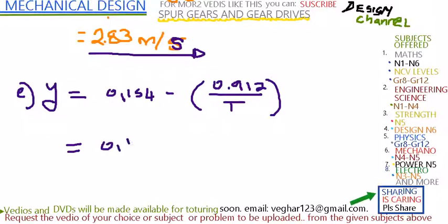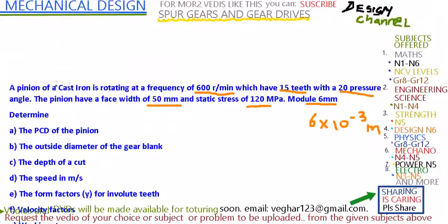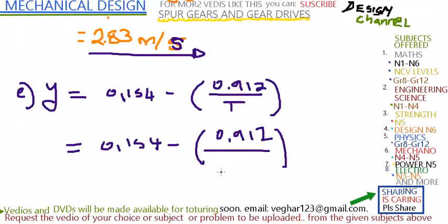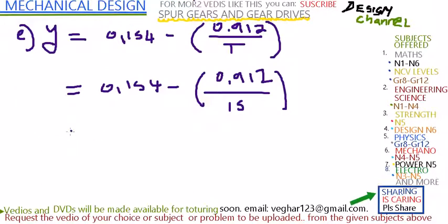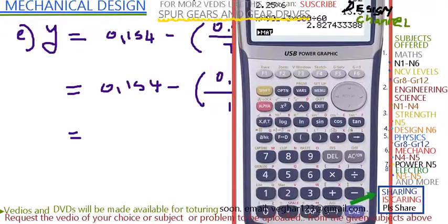So yeah, you're calculating a form factor. So 0,912, and then here the t represents the teeth of a pinion which has 15 teeth. There are 15 teeth on the pinion. So you have to multiply this together. Multiplying this together, what is it?